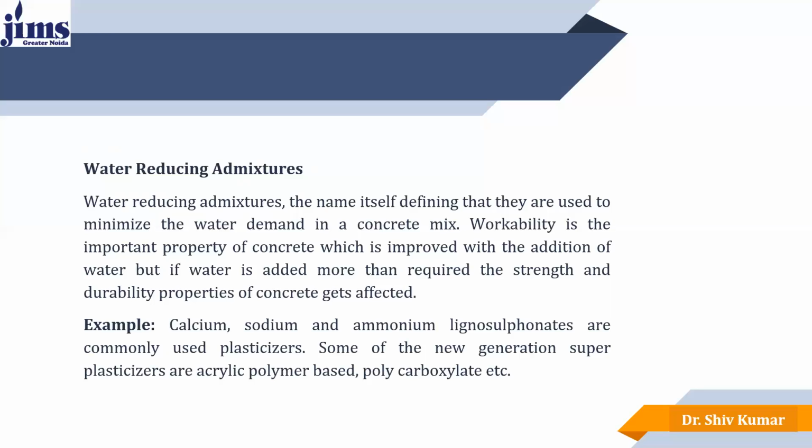For example, calcium, sodium, and ammonium lignosulfonates are commonly used plasticizers or admixtures. Some of the new generation superplasticizers are acrylic polymer based polycarboxylate, etc., which we can use to reduce the water requirement in the concrete mix.